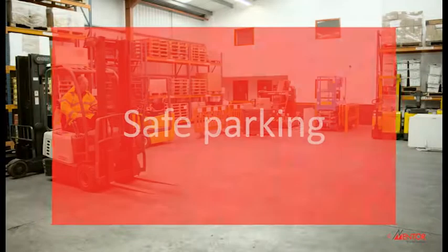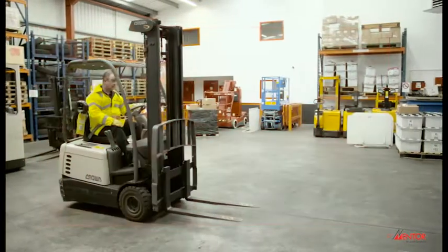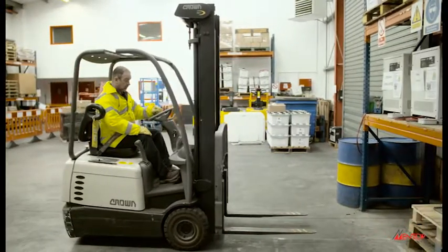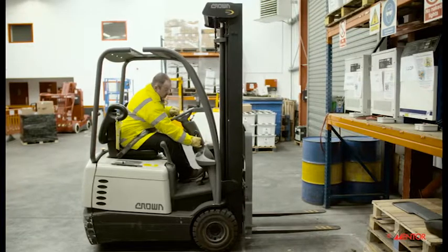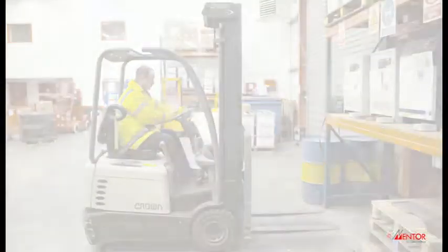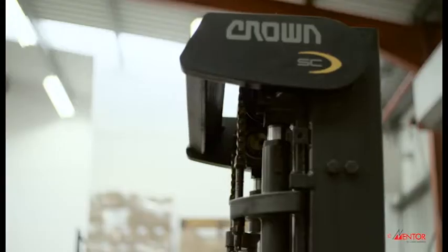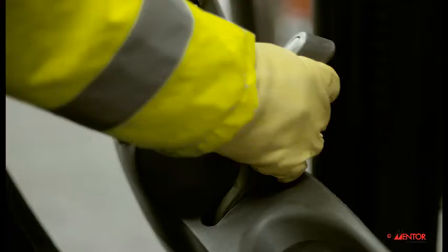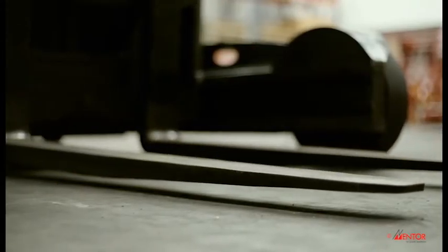Safe parking should be carried out in a safe location where you aren't blocking any doors, especially emergency exits and equipment, or anywhere where it could cause an obstruction, especially pedestrian walkways, as this would force a pedestrian to walk into lift truck traffic areas. The safest position for the truck is on level ground, with the mast tilted forward and fork tips on the ground, the parking brake on, ignition key or fob removed, and on a reach truck, the reach should be fully retracted.